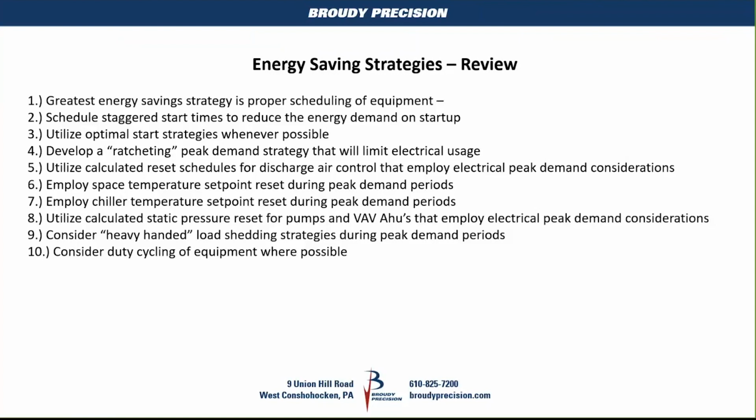This software can do this by either reading a meter and the instantaneous kW, or by counting pulses. You're essentially looking at the instantaneous kW that I'm using. Say I have a target of, I don't know, 10,000 kW, and no matter what, I don't want to exceed 10,000.